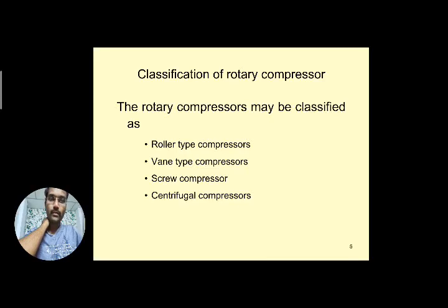We will see the construction. And screw type, in this, the screw is just like a threading that can be seen on it. So in different cases, when the screw is rotating, it gives some translatory motion. Rotational motion is converted into translatory motion. Utilizing this concept, whatever refrigerant is entering may get compressed by changing its section at different cases. And centrifugal compressors depend on the principle of using centrifugal force.